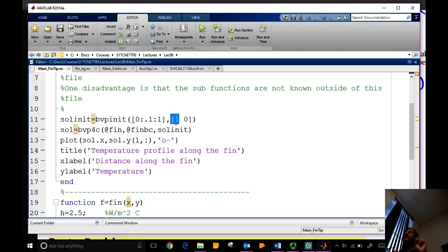So, but it will not satisfy the left boundary condition. It will satisfy the right boundary condition too, but it will not satisfy the left boundary condition. That's the driving force. Heating is starting from the left side, which makes physical sense. If you have a fin at room temperature, theta is 0 everywhere initially, and then you start heating the base, the heat is going to start developing from the left side to the right side,